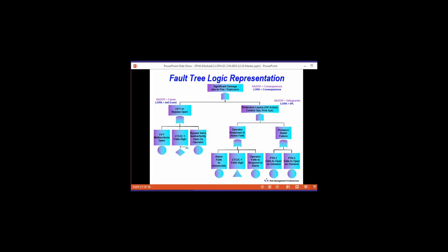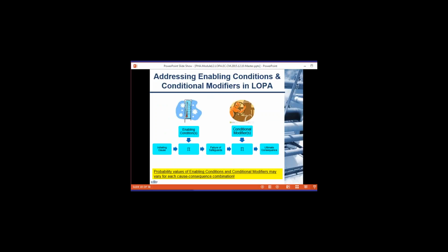Well, in the same way, the LOPA, using different terminology, is really doing the same thing to really clarify what the scenario is and what you can get out of that. For LOPA, you're looking at an initiating event that in a HAZOP is characterized as a cause. In LOPA, you're also looking at the ultimate consequences, and we'll talk about that more on the next slide. And also, LOPA uses the concept of an independent protection layer. It's really a safeguard with an emphasis on its independence and reliability. So all these things come together. Regardless of what technique you're using, understanding the scenario is very important, and we'll get more into that in a few minutes. So LOPA is actually quite easy.